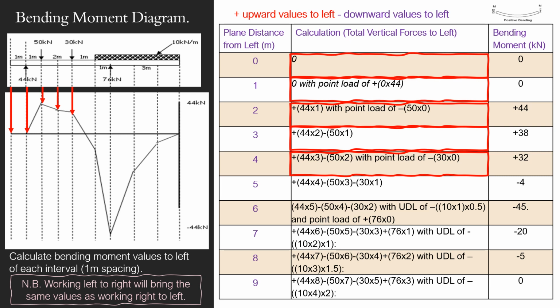And you would just do the same here. So the point load of 30 comes in as well. Not relevant at the point that it arrives, but a metre in, very relevant. And again, you see how this goes from positive bending to negative bending. Again, this is a point to concern ourselves with, because you're bending it in one direction and suddenly you're bending it in the other direction at this point.